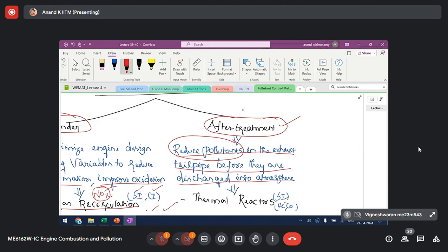So once we start with diesel and ignite, later on we will... No. You have to use diesel as a pilot fuel throughout the operation, because this pre-mixed gaseous fuel-air mixture cannot ignite by itself. So you have to ignite it with the direct injection of diesel. So just to clarify, there is a difference between dual fuel and biofuel.